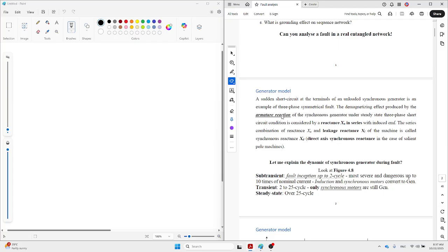So the armature reaction is the negative effect of loading, and then the reactance of that one, because of course the stator and the rotor both are wound and the coil is there. So we will see the effective reactance, which we call XA, armature. The A is coming from armature, which is connected in series with the EMF. The EMF is also considered as a source of energy.